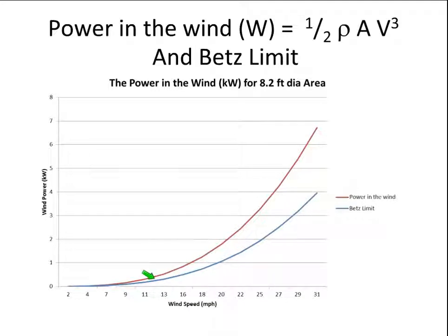So again, if I'm looking at that wind turbine, remember that 1 kilowatt rating, I said 17 miles an hour. Well, I can't catch that much. So the reality is it's got to be closer to 20 miles an hour. And when we show you how much it can actually catch, which I have those numbers following up, that number is going to be out here. So its rating is on a very, very fast wind. That's why we're starting to rate these turbines differently.